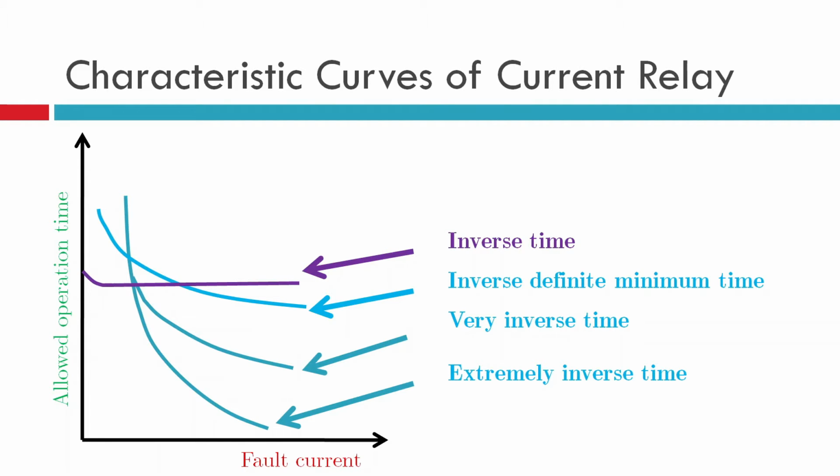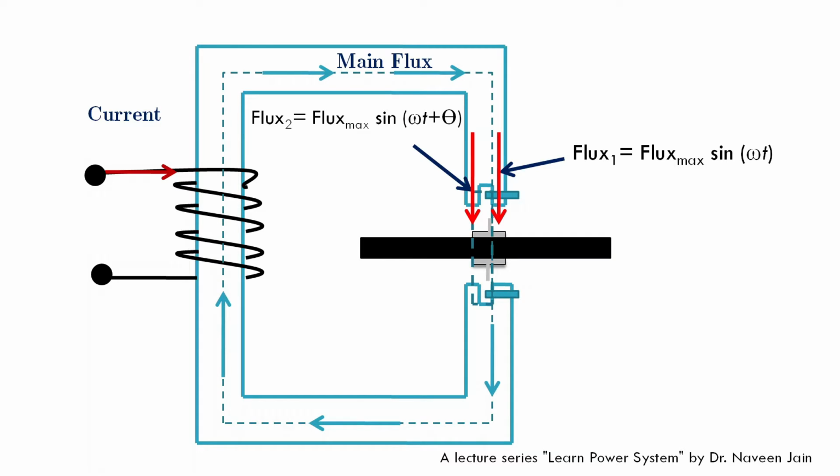So we need to understand what is saturation level for a magnetic material. It is a very important term. Now in this circuit, you can easily understand that selection of different magnetic materials will influence these two fluxes and will change the operating characteristics of the relay. So in field, basically the relays are designed as per the requirement of the protection scheme.